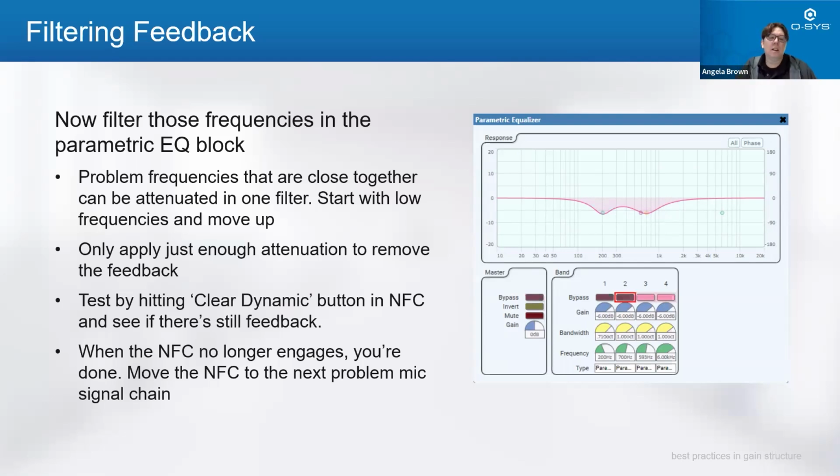And then one thing about low frequencies first, you hear people say this, right? You say, hey, start low and move up. And a lot of times people don't understand why. Every low frequency has harmonics all the way up, right? Sometimes your feedback might be at 1K, but your problem might actually be at 500 hertz. So if you actually start on the bottom side, you might find yourself getting rid of less and less and less as you move up the frequency range of the system.